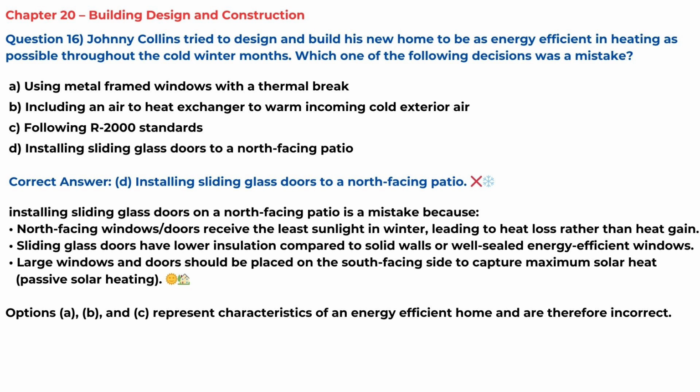Installing sliding glass doors on a north-facing patio is a mistake because north-facing windows and doors receive the least sunlight in winter, leading to heat loss rather than heat gain. Sliding glass doors have lower insulation compared to solid walls or well-sealed energy-efficient windows.